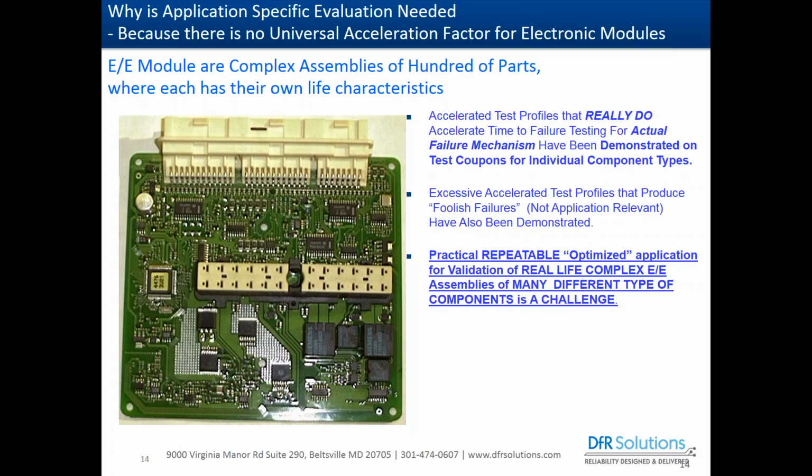So it has been very easy to take one component and put it on a test coupon and develop a very effective accelerated life test. But that won't transfer to the same component being on a different circuit board with different material properties and stress transfer characteristics, and you then put a different kind of component next to that.